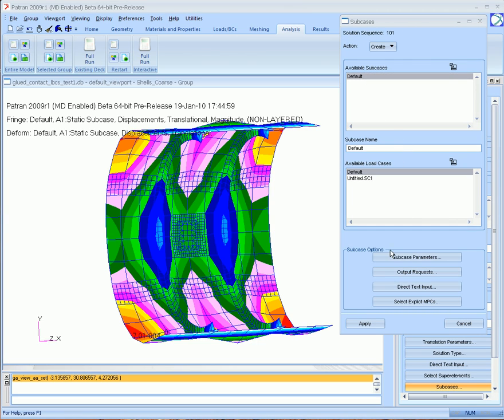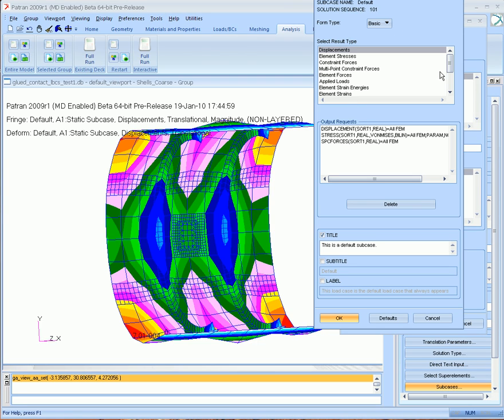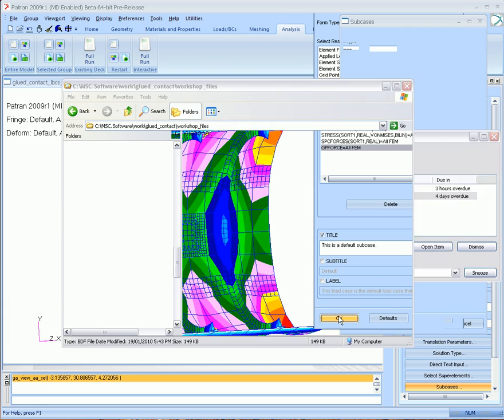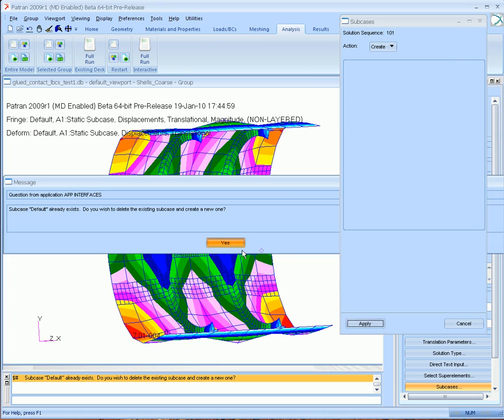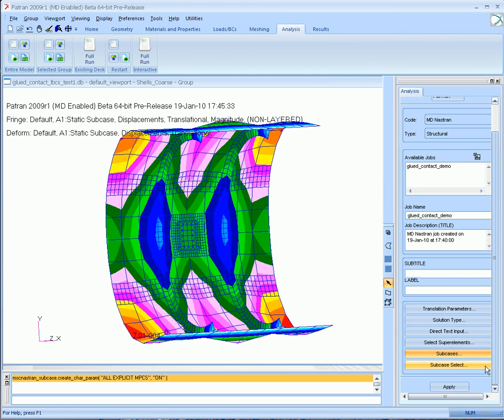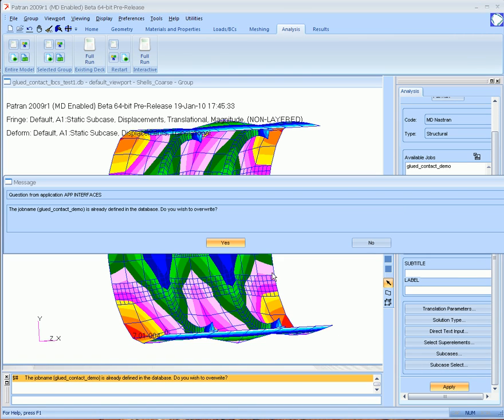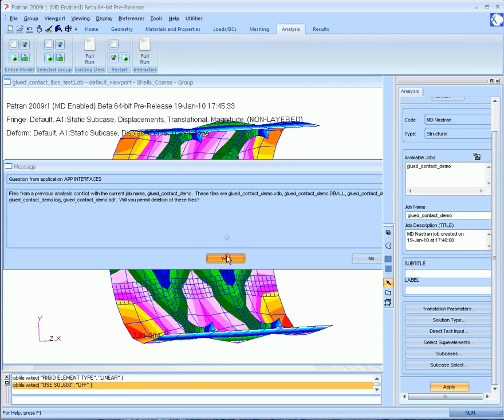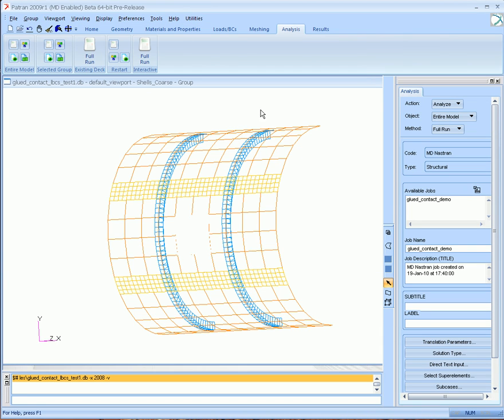and let's do that since it's not too long, we'll request the grid point forces. In this case, we can actually do a grid point force balance, a free body diagram of the localized component. That may in some cases be very useful. So we'll run Nastran again.